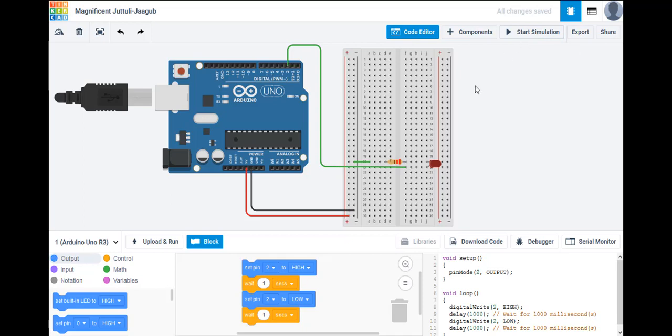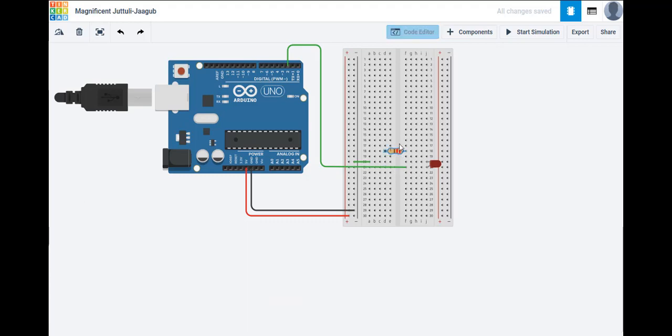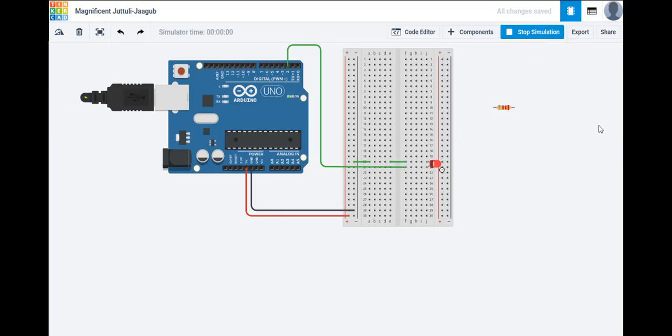I just want to show you why I've put this resistor in. For those of you who have used LEDs before, you'll realize that without this in place, too much current will flow through this LED, and if you'd really connected this circuit without the resistor in place, it will burn out the LED. So let's just simulate that. Connecting across the bridge, and in place of the resistor we've got a short circuit there, and start that simulation up again.